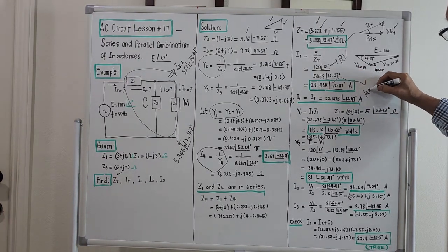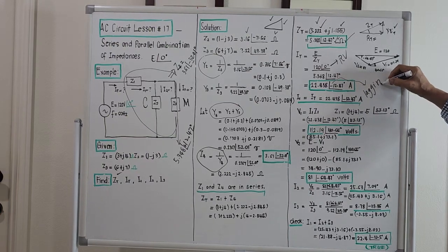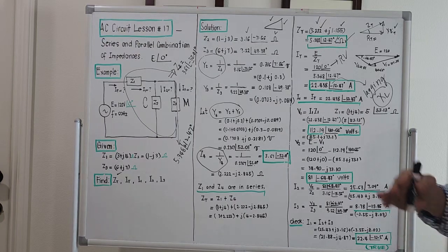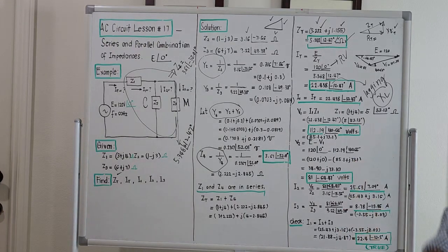The power factor will be lagging, right? Because X of L is the overall reactance that comes out. It's a plus, right? So it's a lagging power factor. Maybe the utility company is still mad at you because your power factor is lagging.